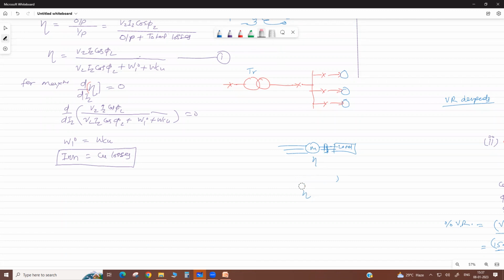Power transformers used at generating and transmission lines are also designed for full load. But a distribution transformer has full load for only a short time out of 24 hours, only in a narrow time period, because this is the maximum demand, so the transformer is designed for maximum demand.